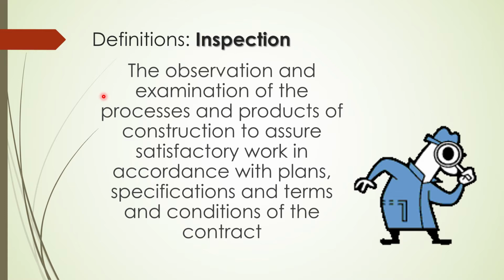Inspection is the observation and examination of processes and products of the construction to assure satisfactory work in accordance with plans, specifications, and terms and conditions of the contract. Okay, there's a lot to know. So when you're going on site, they're going to hand you a spec book and a plan set. Before you even go outside, you better review that specification book, understand your roles and responsibilities, and get yourself familiar with that spec book and plans, because you want to make sure it's being constructed to that.